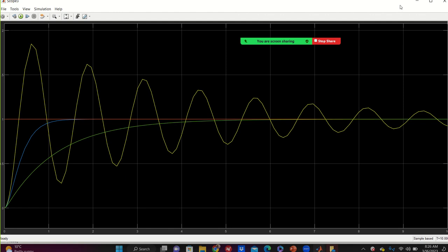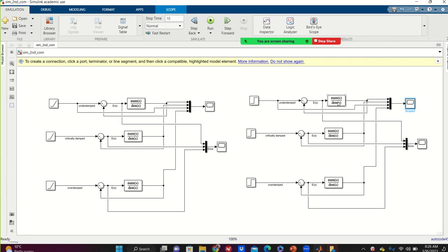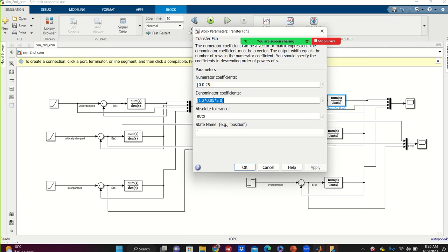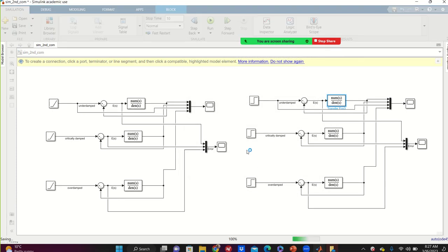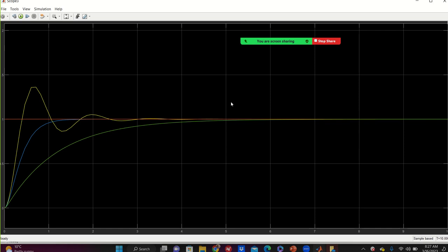Clear, everybody? To make a good vision here, I'm going to increase this underdamp a little more to 0.3, okay, to give you a good picture for us. There we go, see? The maximum overshoot of this is almost 40% because it is 1.4, here is 1. So it's 40% overshoot. That's too much when it comes to control class.